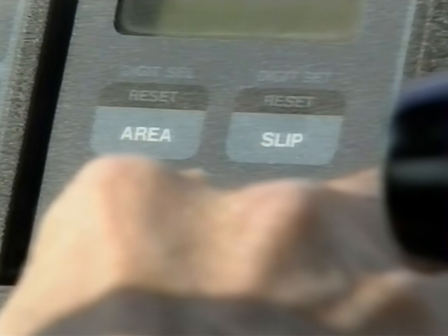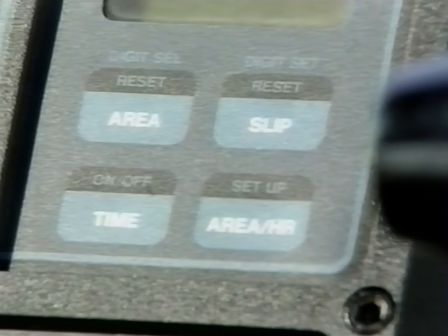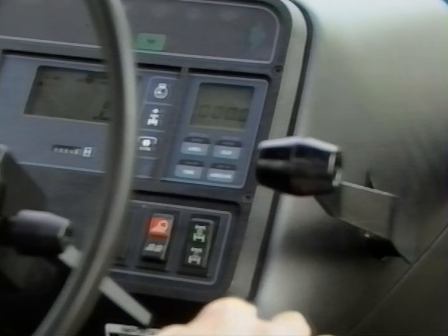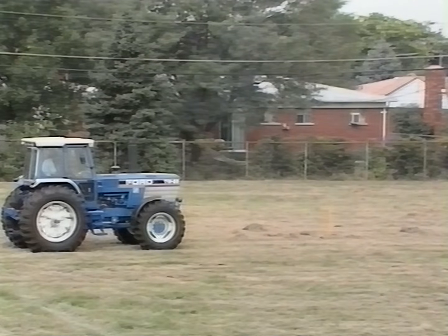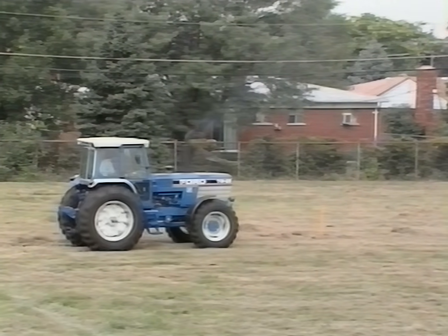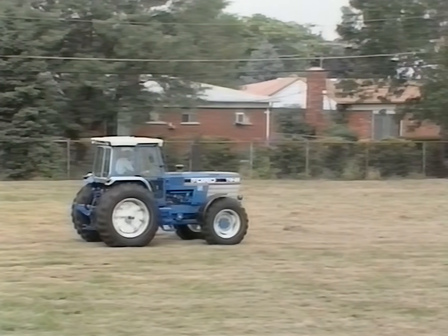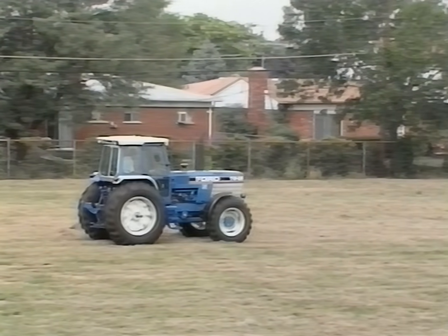To begin the verification, push the setup switch once more. The TPM will clear the calibration number and display zeros on the screen to signify that it is in the verification part of the setup procedure. Once again, you'll need to use a 400-foot course, but for the sake of accuracy, it's a good idea to measure off a different course than the one used to obtain the calibration number.